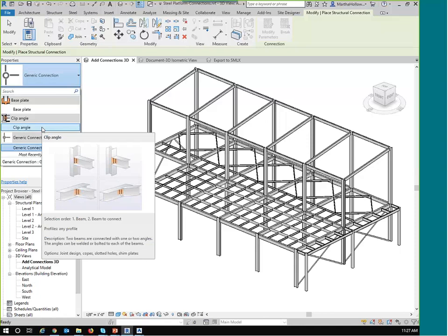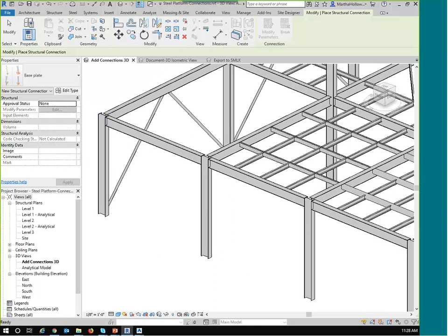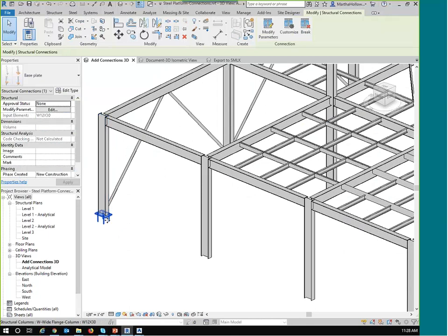One thing that's interesting, when you do Advanced Steel, you know, there's a lot of enters. In AutoCAD, there's a lot of enters. In Revit, you don't use the enter button that much on your keyboard, but you do have to for the Advanced Steel, so kind of watch your prompts. So let me just start with a base plate. I'm going to come down here. Can we see the prompt? Okay, it's not giving me the prompt down there. So basically, what I do is I select it, and then I press Enter, and there is my base plate.